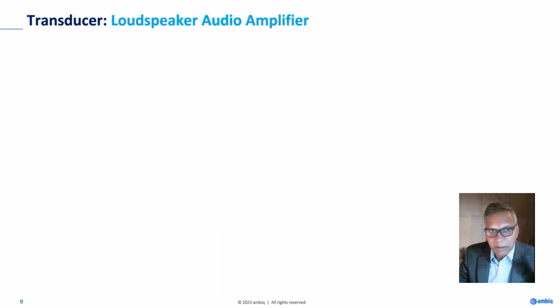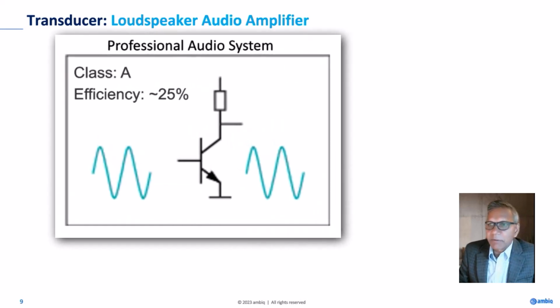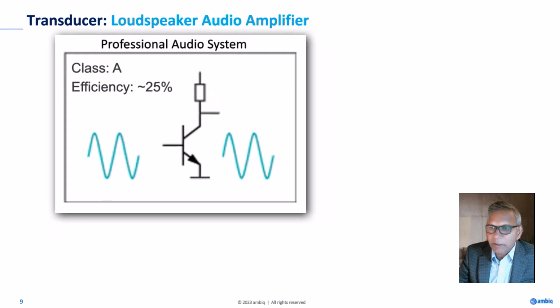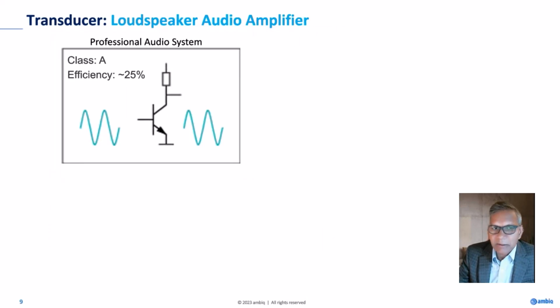So that was about just the loudspeaker. Now, what kind of amplifier will you select? There are 3 types of amplifier. Class A amplifiers are the choice of amplifier for professional audio, but for telco, specifically in wearable form factor, they are not suitable. Primarily, their efficiency is only 25%, which means 75% goes into heat dissipation. In battery-operated devices, that's a no.